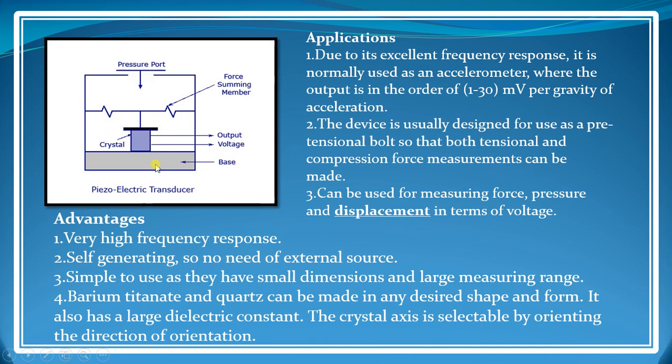Okay, now let's talk about the advantages of piezoelectric crystals. As we understood in the previous example, it has a very high frequency response. Self-generating, so no need of external sources. Simple to use, as they have a small dimension and large measuring range.